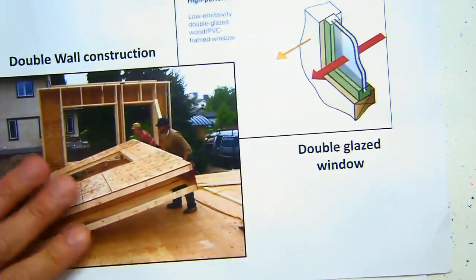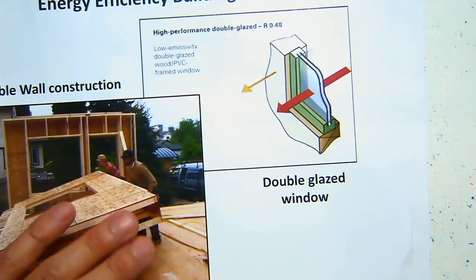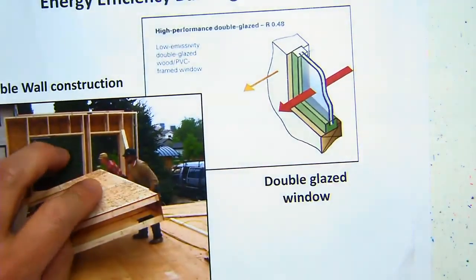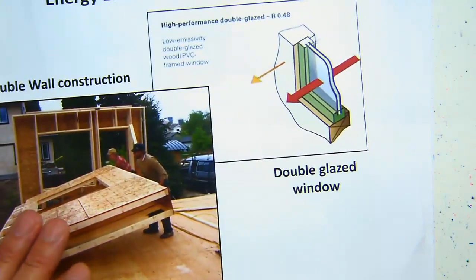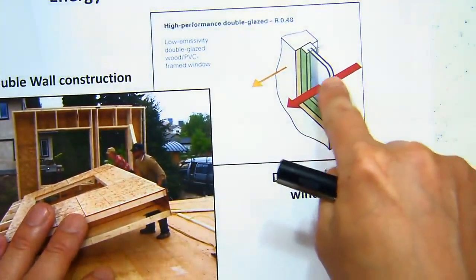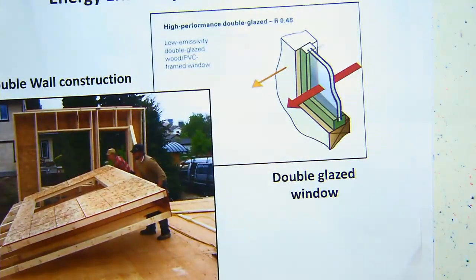And in terms of glass or windows, that's also a similar idea. This is the so-called double glazed window. You have basically two layers of glass, and one layer of air sandwiched in the middle. So the idea there is that you have a layer of air which has very low thermal conductivity. So in summer, if the inside is cool, it can prevent the outside heat from getting in. So basically, it's a thermal barrier or thermal insulator.